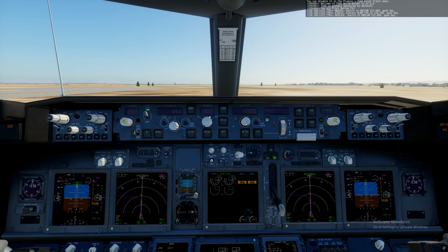He gave me, if you remember, the ATC gave me clearance to climb directly to my flight level 150. Sometimes they give initial climb and then they clear you to your flight level, but in this case he just gave me a straight ahead clearance to go to my flight level. The heading is going to be the same as the runway heading. Our runway is 22, so in Larnaca runway heading is 220.